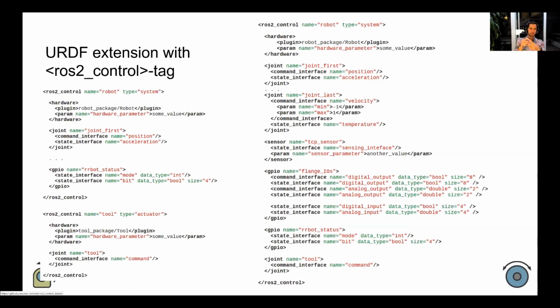So you can use this as it is, but the problem I see is you don't have any guarantees, for example, when your message will arrive at the microcontroller, because at least the current implementation of DDS didn't show itself really real-time safe in these terms. Of course, it depends on your hardware setup. And another thing is, what if you want to do something more complex? For example, synchronize this with robot movement.